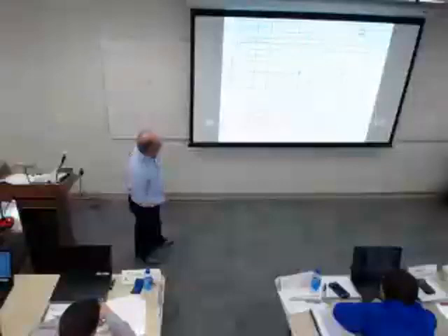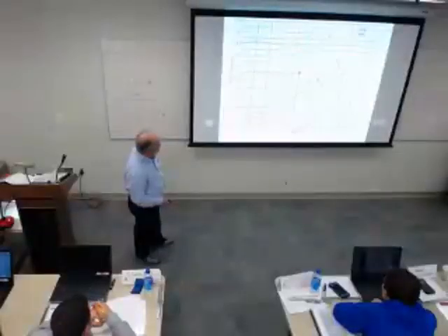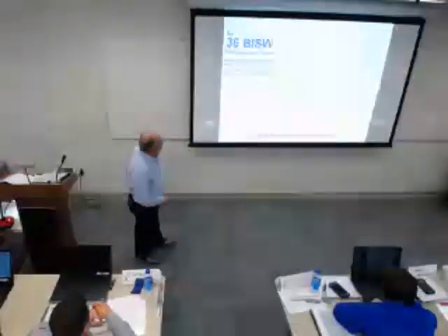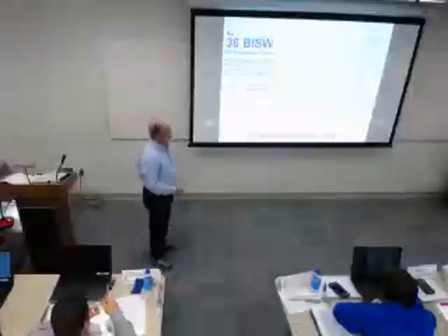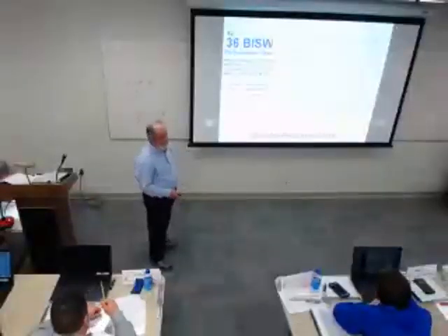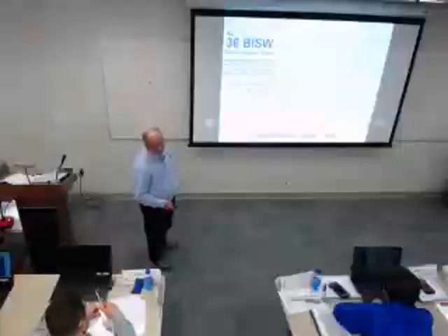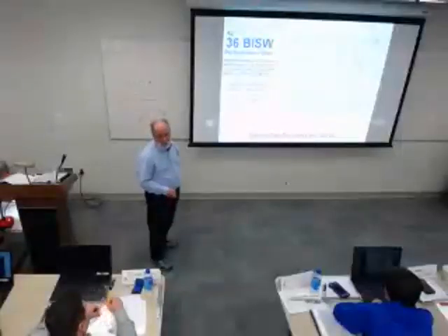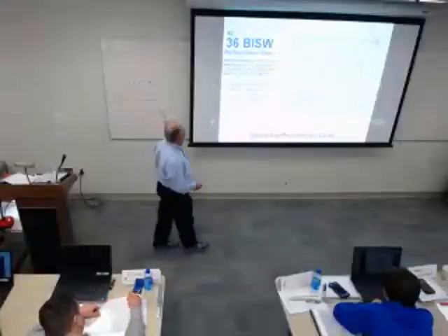Let's see here, the 1200 RPM. Yeah. So we're in between the two, we're going to have to sheave it, and the motor's going to have to be big enough to carry the load now. And that sometimes affects wiring, always affects some of the other electrical components.